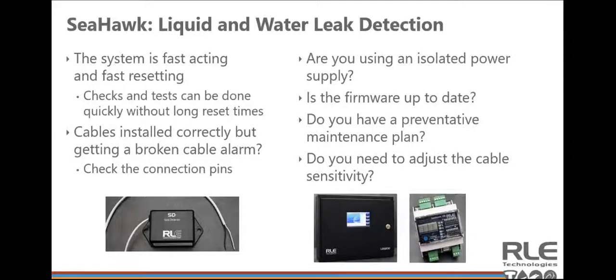Dirty cables, major construction where they come in and accidentally cut a cable or cover it in silicone that blocks the conductance or the sensitivity of the cable. We've seen all sorts of problems. So perform a yearly maintenance at minimum. Test the system, make sure it works so you're not surprised by anything.